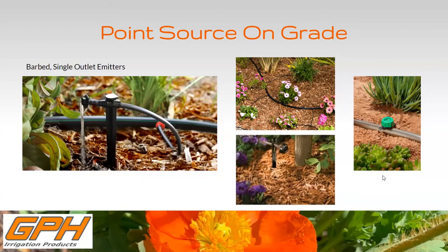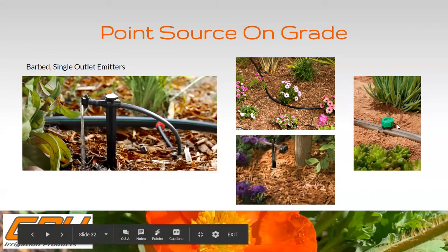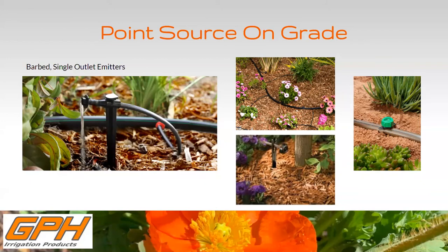Depending on your plant's requirements, you can choose emitters with different flows. The flows of the emitters vary, but they are typically preset. For example, most manufacturers offer 1/2, 1, 2, and then it gets larger to 4, 6. You can choose emitters and figure out the hydraulics based on your plant's requirements. So this emitter here could be a larger flow and be watering both of these plants depending on the watering schedule.